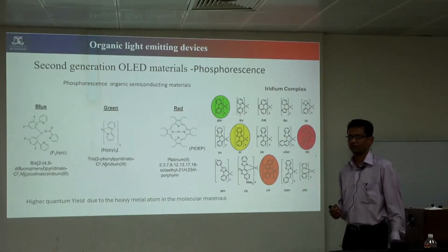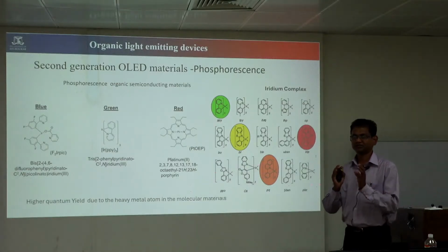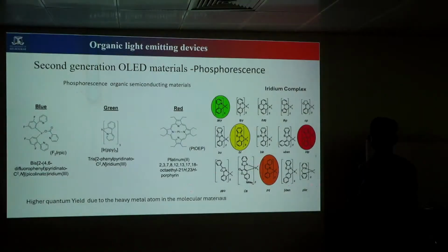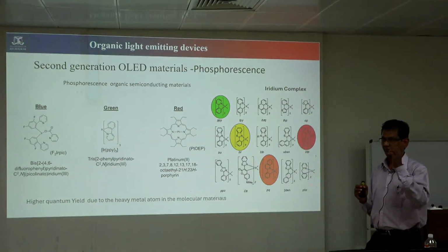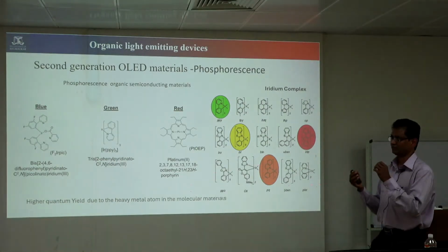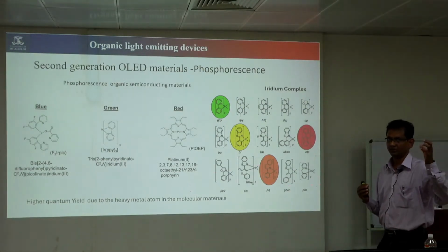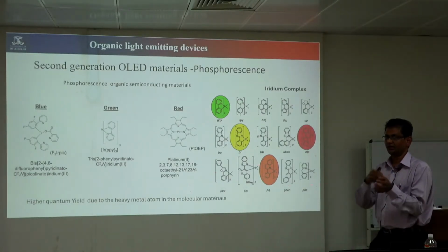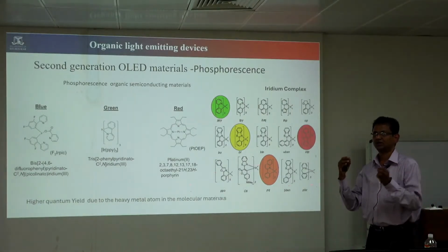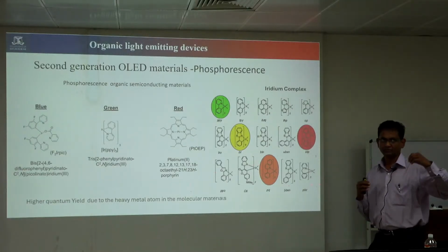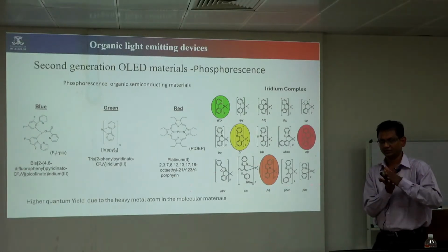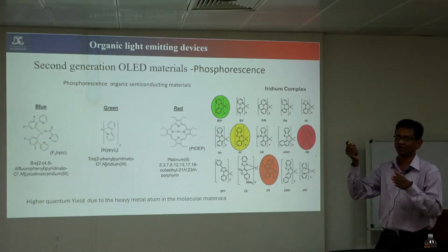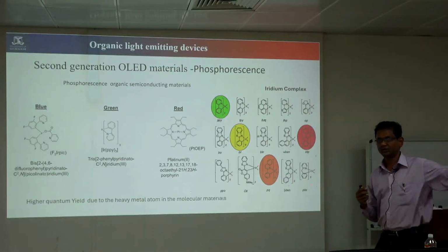I am talking about EQE. Again, I am saying that EQE is something different from IQE. IQE means whatever light is absorbed by the layer, and then whatever emission is created. The photon is actually absorbed by the layer and how many electrons are given, that is called IQE. But EQE means the total influx.